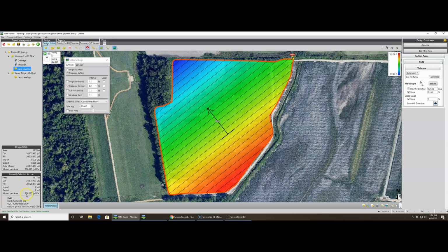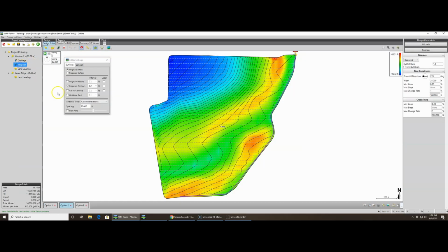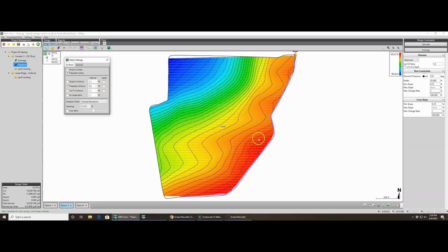Okay, so best fit, you have 736 yards to the acre, and this is the high. We would not like this because our well would have to be over here. But anyway, best fit straight grade versus variable grade on this particular field. We would have to build us a pad up here to drain water off of. Everything would work. Our high would be right here. So we would need to build a flat pad all the way over here, but again, we're 415 yards an acre versus 700 and something. So that's definitely 40% better, for sure.